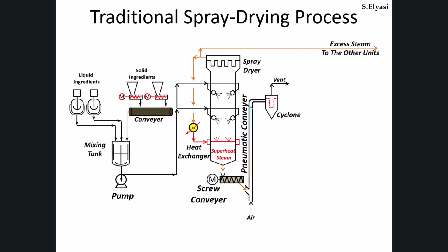Dusty gas enters tangentially, a vortex forms, particles move to the wall and fall to the hopper, and the cleaned gas exits through the top. Key factors include inlet velocity, cyclone size, pressure drop, and powder properties. Very fine or sticky powders may require multi-cyclones or a downstream filter.